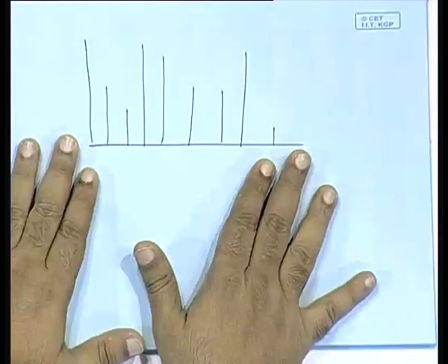So, in the design process, we are trying to find out how much should be the rating of the turbine, how much should be the reservoir capacity, how much should be the spillway capacity. That means, during the flood time, you will have to allow the water to flow without going through the turbine. So, what should be the size of the spillway capacity? All these designs have to be done. Only this data will prove to be not very useful for this purpose.